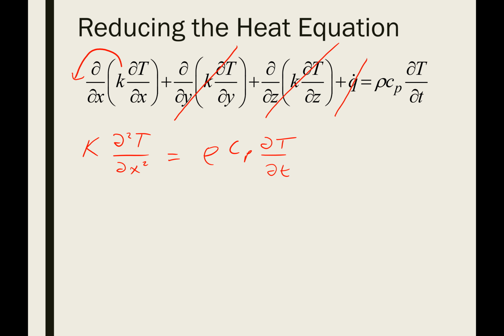To make the math a little simpler, the book will go through some lengthy solutions to these equations and deriving how you get the transient temperature profile. So they start off by lumping terms. One of the terms is called alpha, and this is defined as k over rho Cp. This is called the thermal diffusivity.